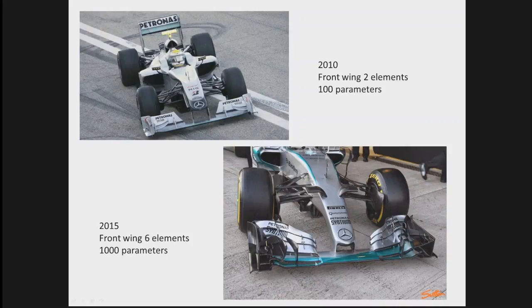The camber is very high because the chord of the wing is very short. So you can imagine each element is very loaded locally. If you only keep 2 elements, you cannot keep the flow attached. You're going to separate.